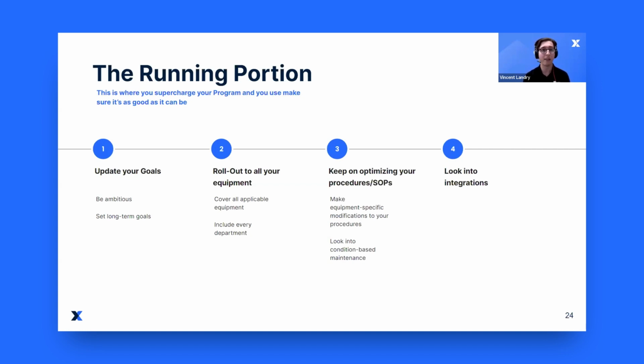So if you have an equipment that has 3 greasing points and another one that has 4 greasing points, and your procedure was more global about, okay, well, use the greasing points to do your maintenance, you can start really creating some unique and asset-based procedures. And you can also start introducing pictures in there to really give a visual support to whoever might come in the future in your team or whoever needs to perform the maintenance.